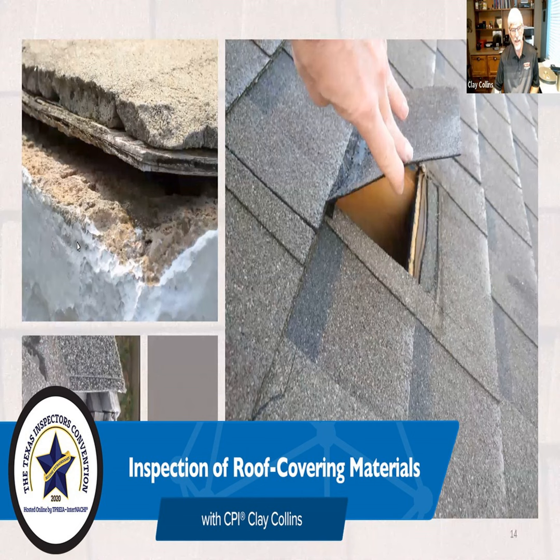You're not going to see overdriven unless the shingle is ripped out during wind because it's lost its adhesive. Crooked you might see, but this is what you're going to see more often than not, and you're going to see it in something like this. Now, this doesn't really look like they underdrove the nail. This looks like the nail worked its way back out.